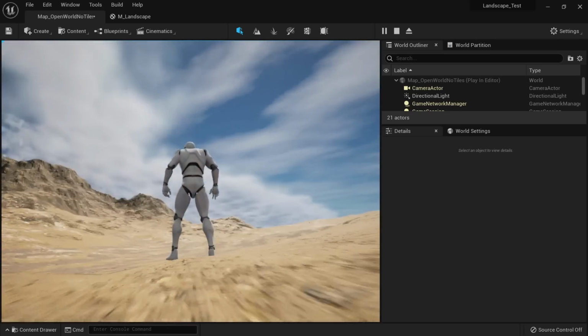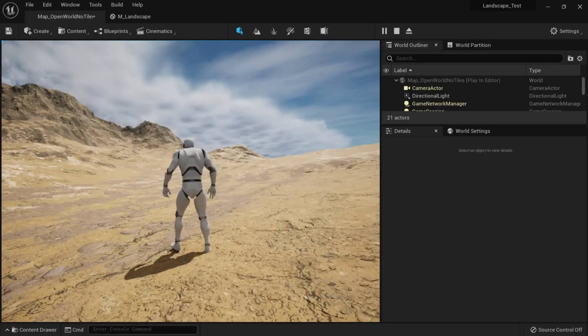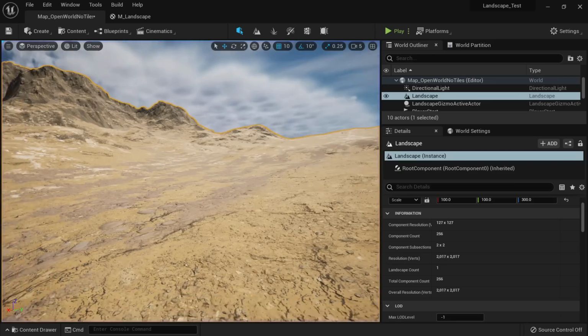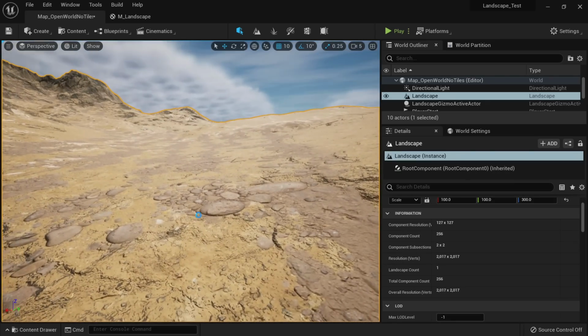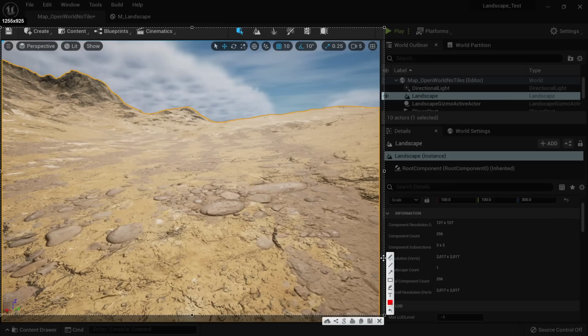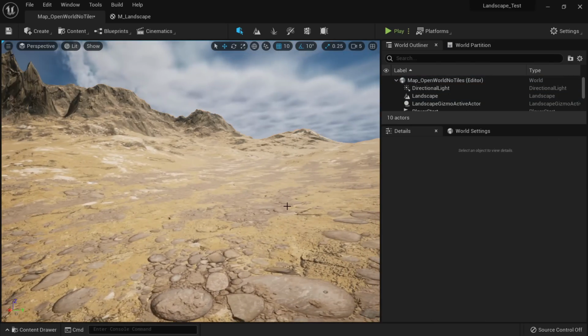So in Unreal Engine 4, we had the world displacement, which we can multiply by the vertex, and it will push the height information of the texture so that this one goes high based on the texture that we have. And this will give us more realistic details. So we're going to do that.